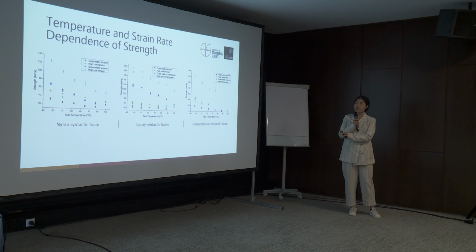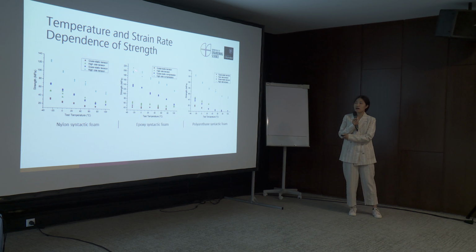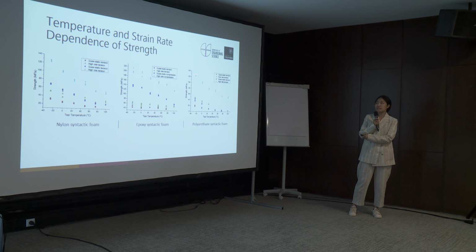From our experiment, it has been found that there is temperature and strain rate dependence of the strengths. With this scatter plot, it can be found that the compressive and the tensile strengths increase with the increase of the test strain rate and decrease of the test temperature.